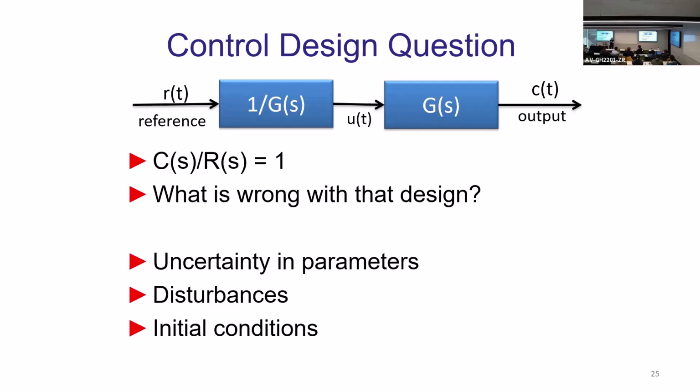So your 1 divided by G will start from a completely different initial point, okay? And they might not even converge to each other, actually, because you have open loop and you don't have any way to control where that system is right now, what state it is in right now. What voltages? Maybe it was already rotating at the beginning. Who told you that it was at 0 angle and 0 speed when you started to give your step response? Maybe it was already rotating from a previous stimulus or whatever. You don't know. And you don't have any feedback loop to correct it.